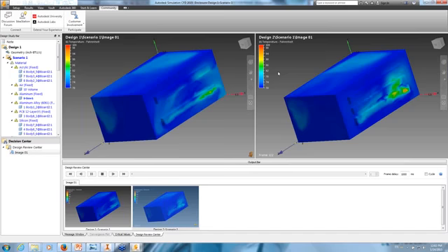Yeah, so remember, a question just came in. I saw Paula respond back about results mode. Can we select by group? You need to set up the groups within the pre-processor first so that it comes over in the post-processor. You can't set up a group in the results because it's brought through from the solver. If you do want to create a group, create it in the pre-processor and then rerun your analysis for 0 iterations, and that will then update that group and have it in the post-processing result side.